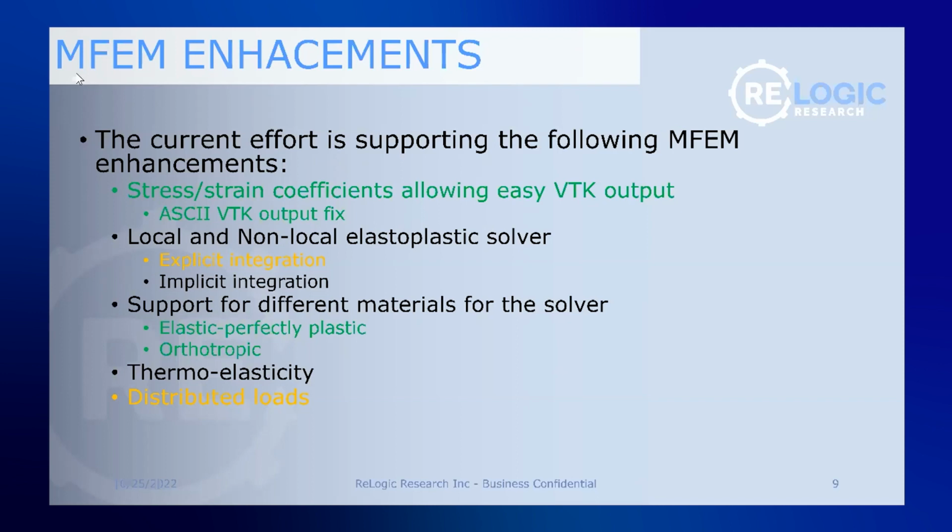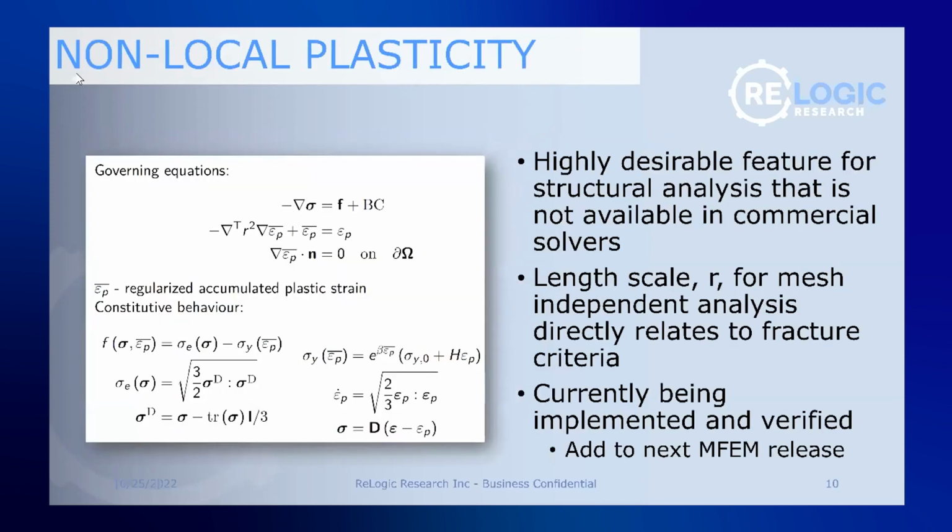We're also adding some support for different materials in MFEM, obviously elastoplastic, but also orthotropic materials to analyze composites, and then also going to work through some simple linear thermoelasticity, so some sort of temperature field and CTEs to get thermal stresses, and then finally some distributed load cases, so complex pressure or traction distributions on surfaces, and all those enhancements will be open and in the code, hopefully.